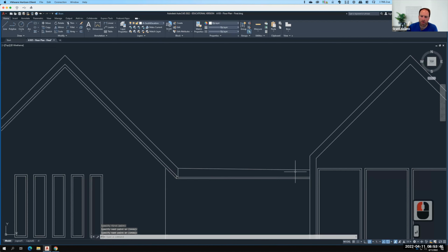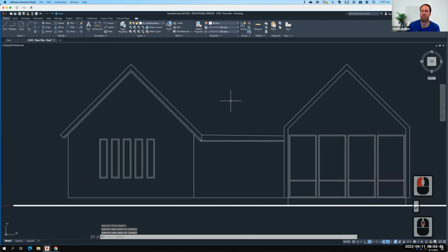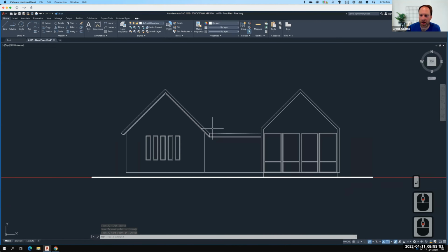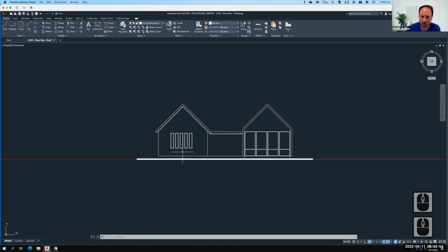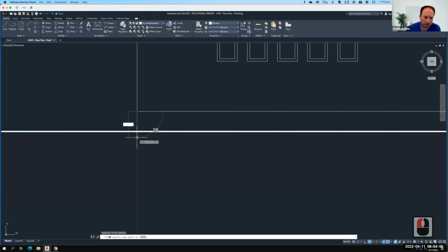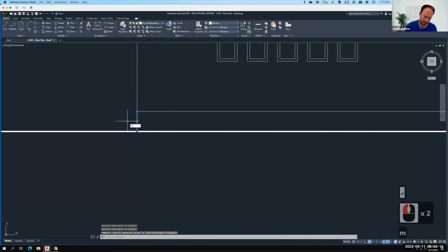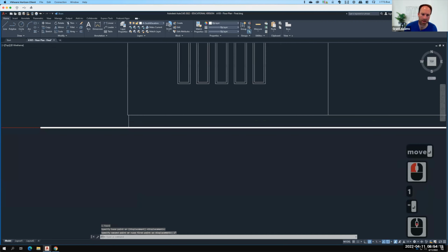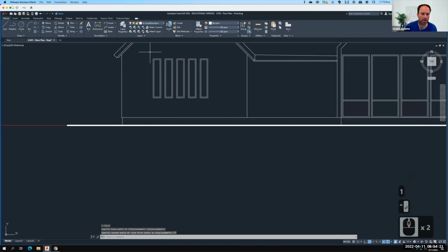Like that. Now, I don't exactly know where the upper part of this roof is because I haven't really figured that out yet. So I'd have to figure it out in one of the next elevation views. But this is starting to get really close. So let me go ahead with my line tool. And I'm going to need to draw in the foundation. And some people will just draw this straight down here to draw in that foundation. From a technical standpoint, there's usually a little bit of a reveal. So I like to move this over by at least a 1/2 inch to an inch. So I'll move it over by an inch just to have a little bit of extra detail. Let me draw that one in.